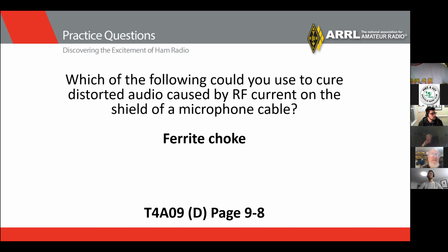It's probably about 1 inch long and about a 1/2 inch in diameter. That is the ferrite choke. It stops the RF signals from getting into the computer or speaker and coming out of the computer. This is also on my power supply brick to keep the noise down.